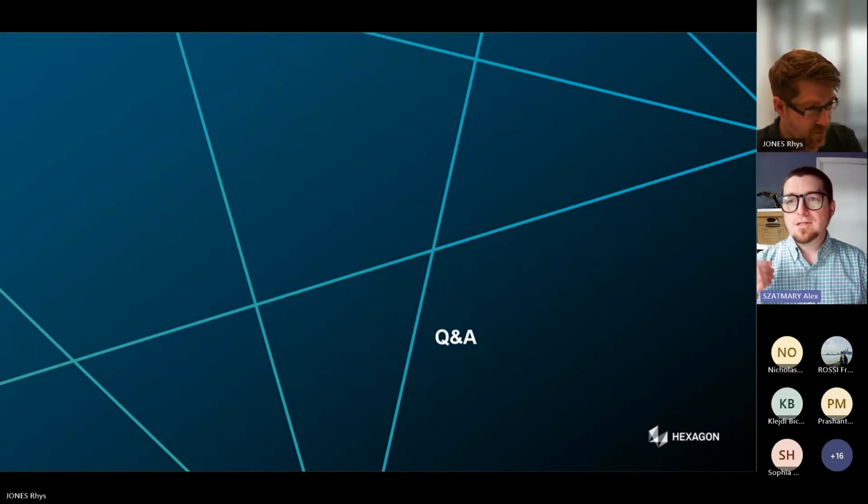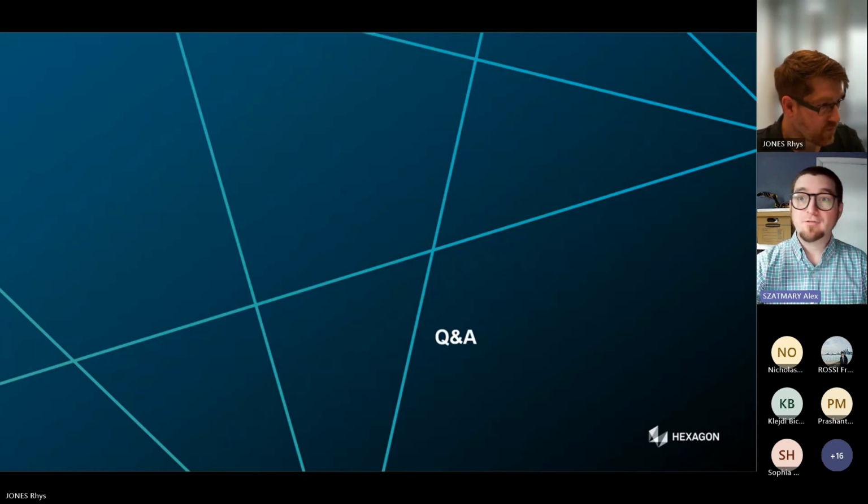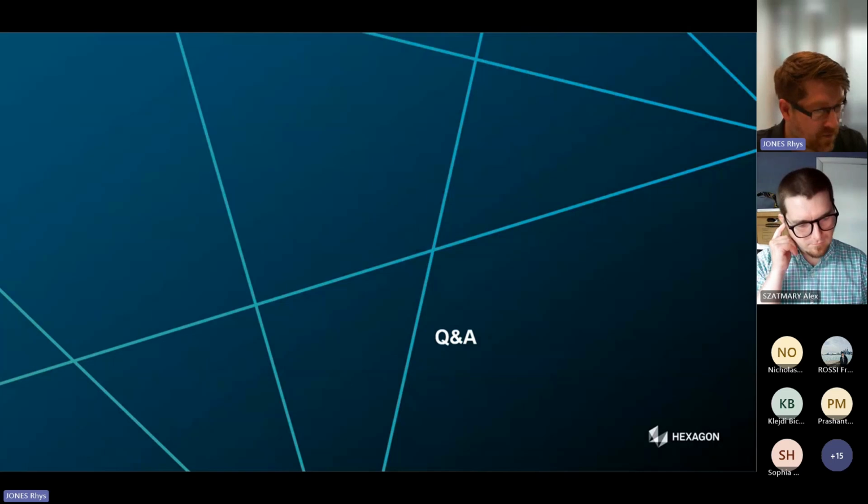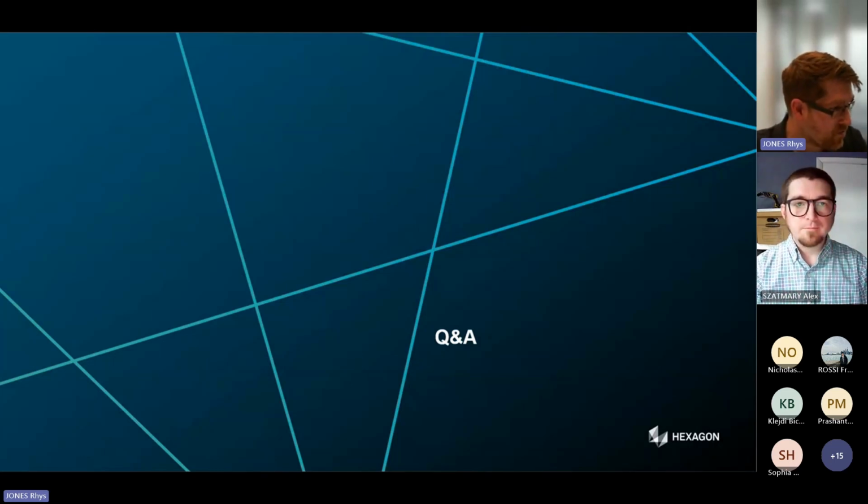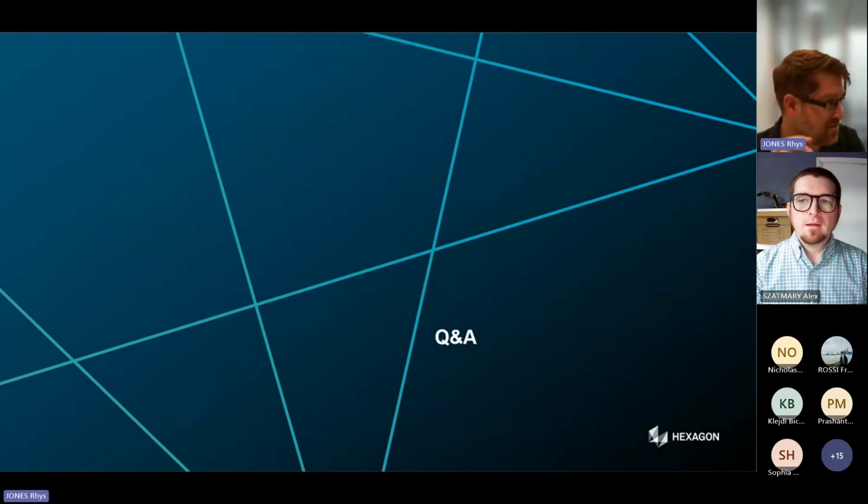On that note, Reese, you had mentioned the term super element, and I wonder if you could just provide a brief description, especially for somebody who maybe is already aware of finite element analysis, but is used to doing that on a single part or a couple of parts. Yeah, so a super element, effectively, even those simple FE components that we had in our model. So those components had 100,000 elements, made up of 100,000 little triangles, little tetrahedrons.